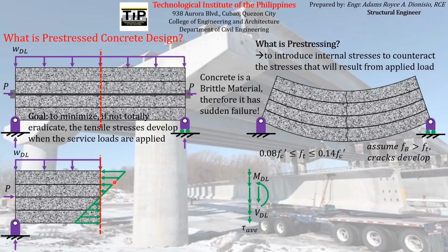Obviously, on this cross-sectional area. So, there will be an internal compressive force that will act on this cross-sectional area in addition to these internal forces, shear forces, and bending moment. And just like the bending moment and the shear forces, actually we can call this axial force because obviously according to the drawing or the figure, it acts along the axis of the concrete beam. So we can call this axial force.